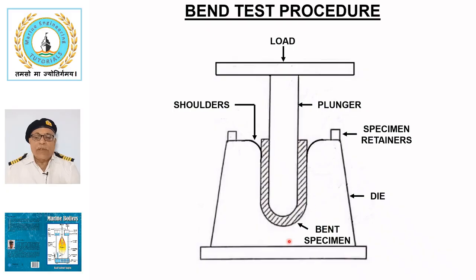After the bend test is completed, the specimen is checked for any cracks which should not appear if the material has undergone proper heat treatment. Typically, 3 tests are performed and the results are averaged. This test is particularly useful for detecting changes in the material caused by heat treatment, hot or cold working and casting, which cannot be identified by other testing methods.